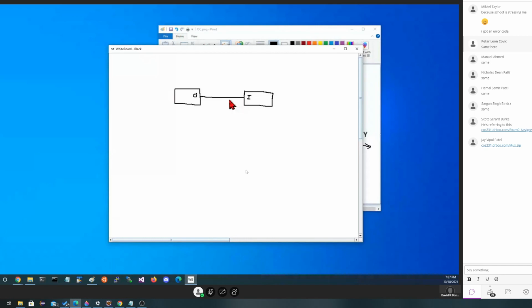So instead of just leaving the circuit as a wire going here, let's add what's called a pull-up resistor right here. I'm going to call it a pull-up or a PU resistor, pull-up. And it's going to be hooked to, let's say, plus 5 volts.